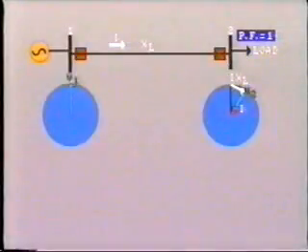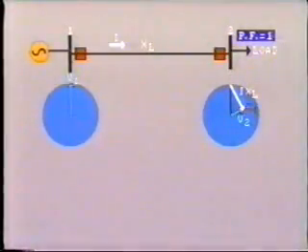As a result, the V2 voltage will lag with respect to V1. If the load demand at bus 2 increases, there will be an increase in current flow, so the voltage drop, IXL, increases like this. Consequently, the receiving end voltage, V2, lags further behind V1. The power angle, phi, increases as load increases.